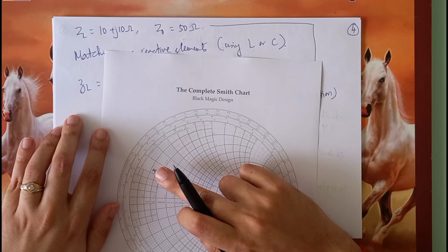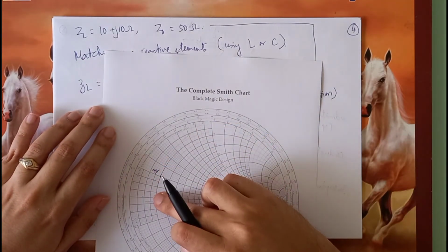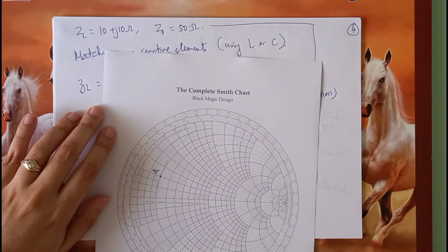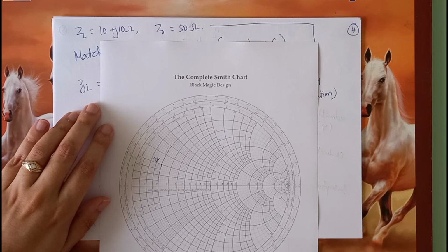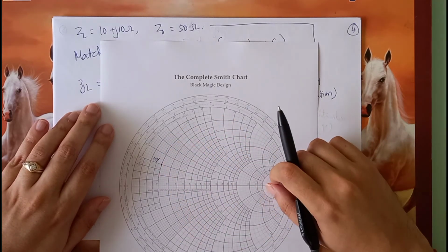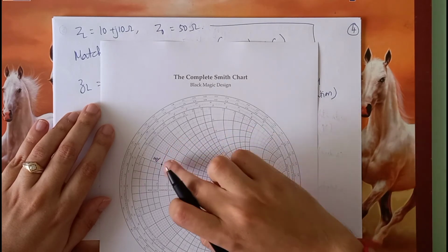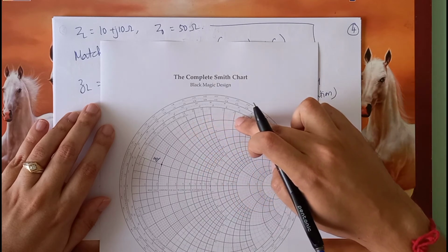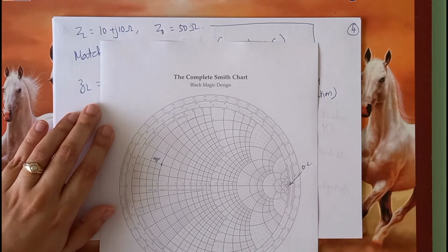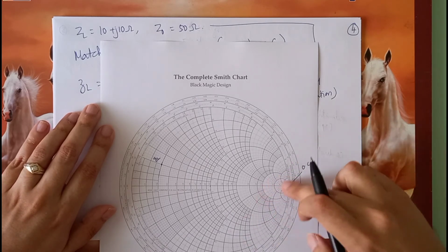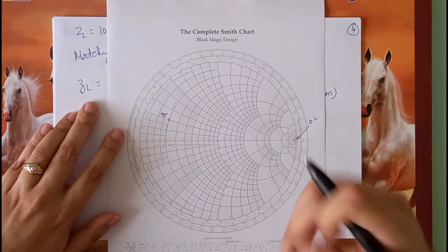Okay. Now one thing to remember is that this is not a VSWR circle. So moving up or moving down on these circles has no meaning on whether it is moving towards the load or away from the load. Okay, so that confusion, you can simply put out of your head. So now the question is, let us say I am over here, which we are, and we start moving upwards. Even when we are moving upwards on the circle, we are coming here, and then we will come here. So it's not serving any point. This is the open circuit point. And then again if we move, we are coming back to the same point on this circle. So it's not really working.